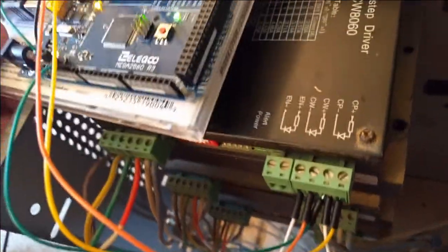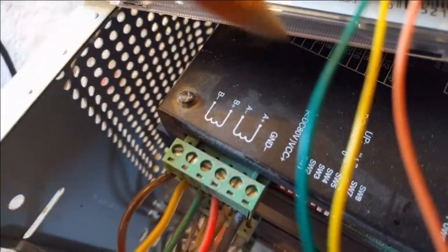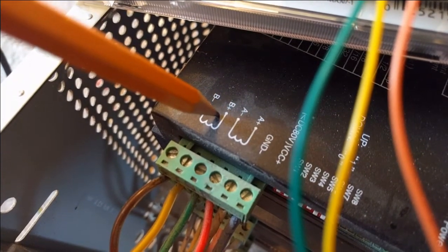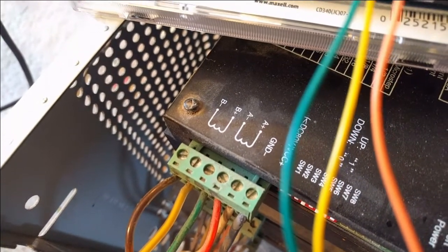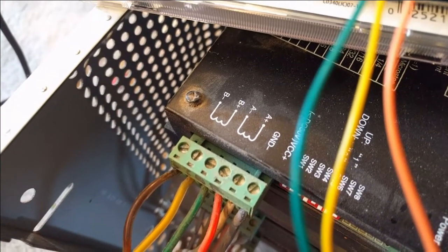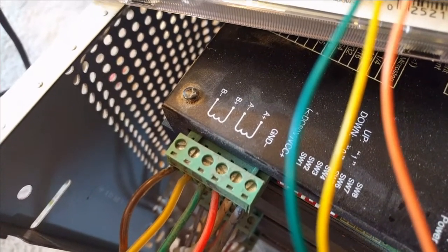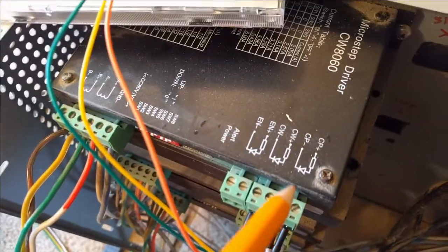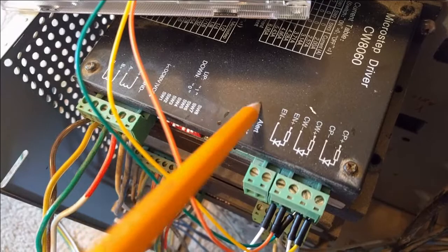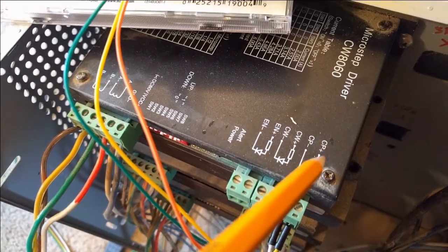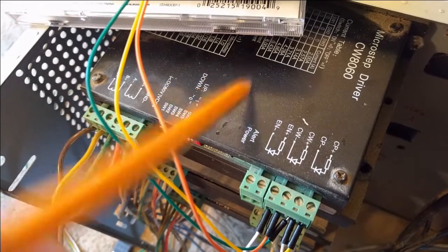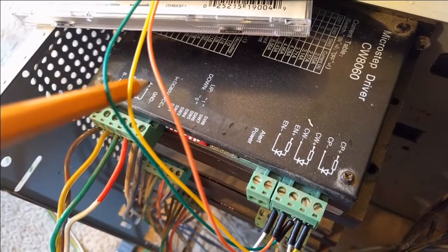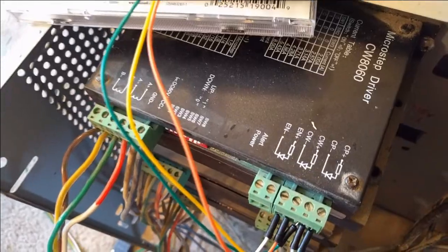I had some confusion in the beginning because what bipolar stepper motors do is they split up A and B pulses so that it has great control between two stators. I'm not sure exactly what it is in the motor, but this allows it to step. Now, I thought I had to send two different signals for A and B to this unit, but I don't. I just have to send a go signal, and then this thing separates the signal to power the motor appropriately.